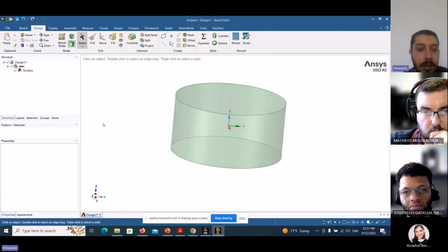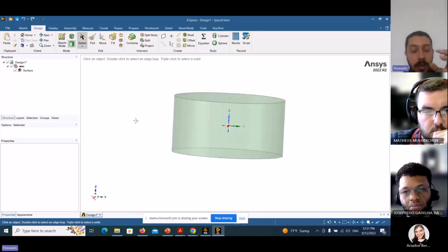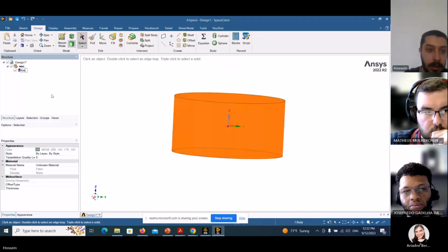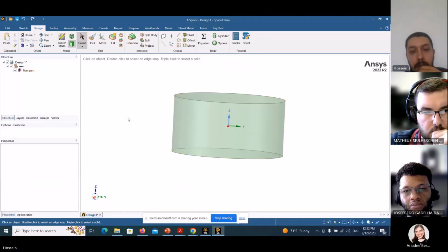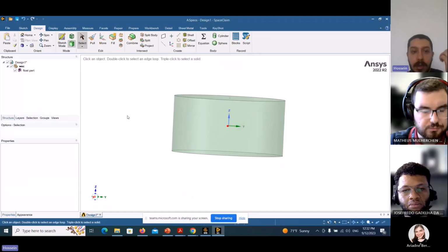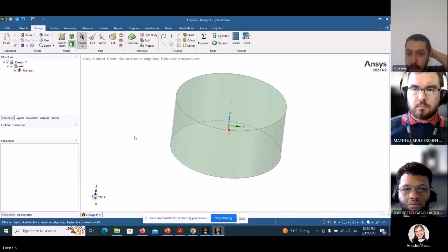we can see that we have a one part structure that is a surface and consists of a shell, and we can rename it to float part. You can make your solid parts with this manner to make them shell parts, and then import it to your ANSYS AQWA and analyze them.